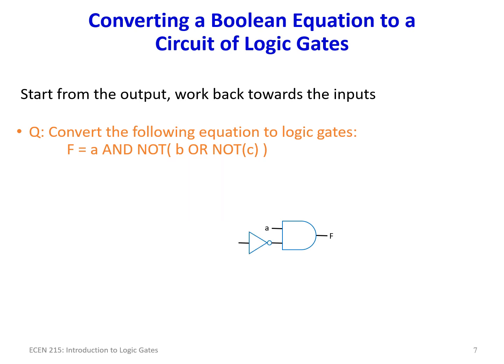We put the not symbol in, so we've implemented this portion. Now we have to create the circuit for this, which is an OR, and we get this from here. So again, kind of highlighting where all this is going. This is the AND. The not is this part, and the OR is this. And so we have B, and we have a not C. So the next thing to be added is just simply the B, and then the not C.